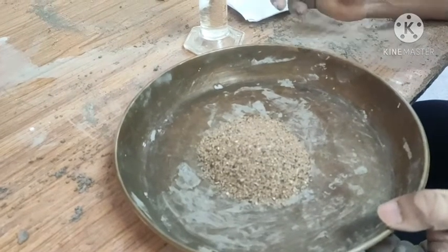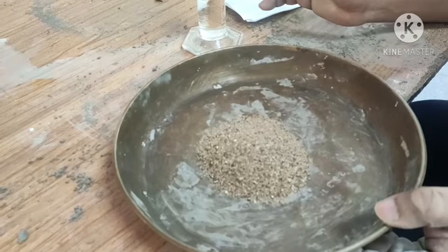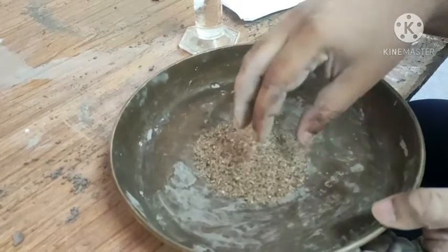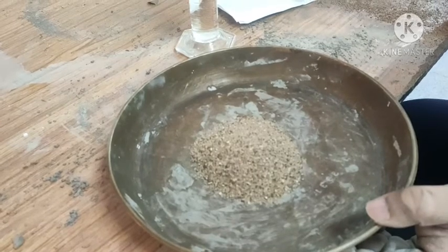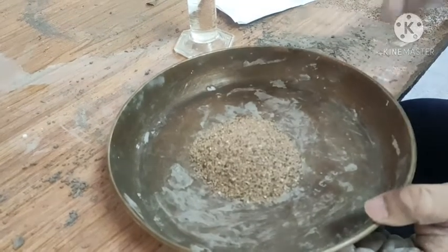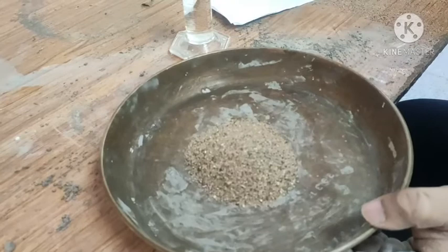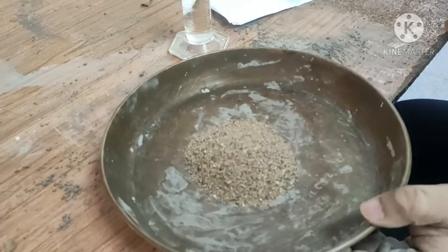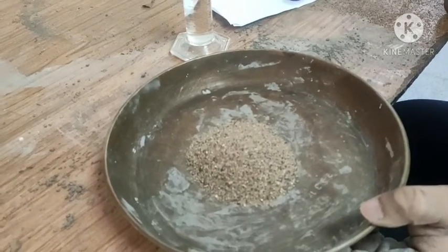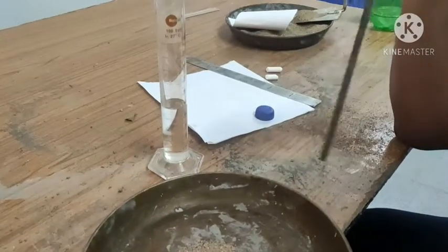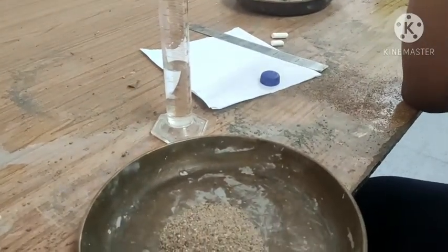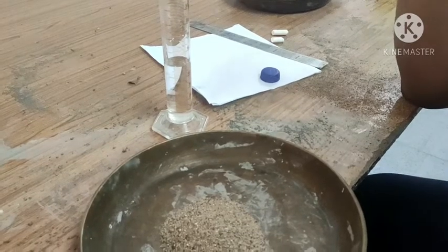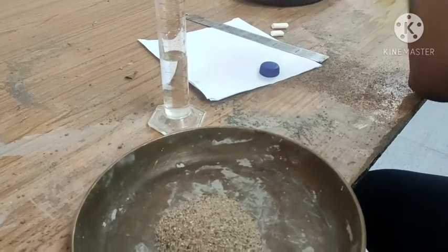Then what we will do next is put this sand into this cylinder filled with water in two phases. First the half portion, then we stir it with this steel tamping rod that is 6 mm in diameter. Then we will put in the other half and do this procedure again. And finally, we will measure the height. Okay, let's do it.